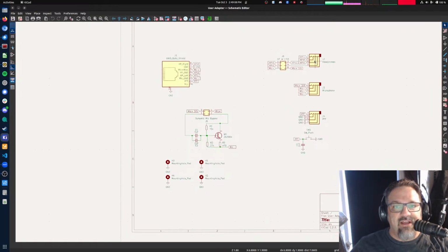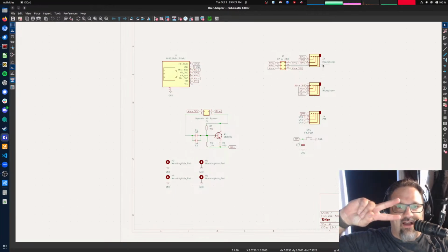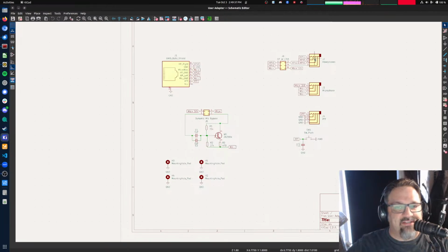So this user adapter, assuming you can connect your stuff into a 3.5 millimeter headphones, a 3.5 millimeter microphone, and a 3.5 millimeter PTT, or use the built-in PTT. As long as you can get the connectors to work into that, then this will work on either a two-plug, like a Heil headset, where you've got a separate headphone and a microphone, or a single CTIA, like a PC gaming headset, the 4-pin stuff, whether it's a dynamic or an electret mic, all of that to work with OHIS. Pretty snazzy. And very simple, right?